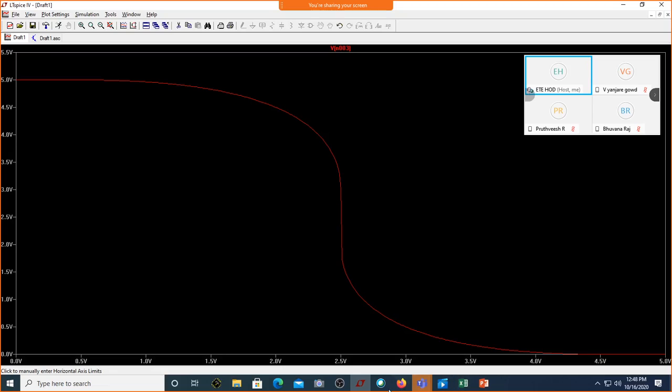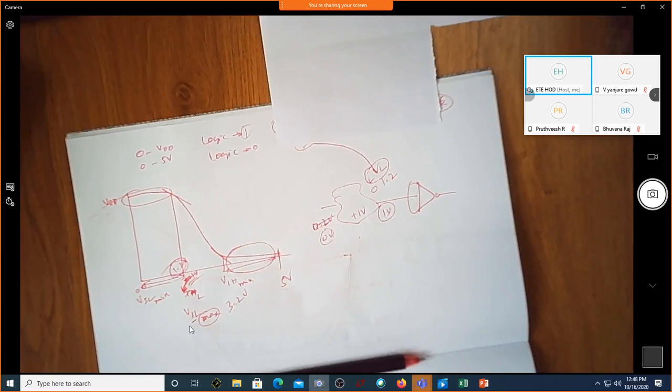Suppose the input voltage is well within this range, between VIL minimum, which is usually 0, to VIL max, which is decided by the dimension of the transistor. We will see how it will happen. So in this case, 0 to 1.2 is the range of input voltage which can still be considered as low voltage. And anything beyond, let us see what this voltage is.